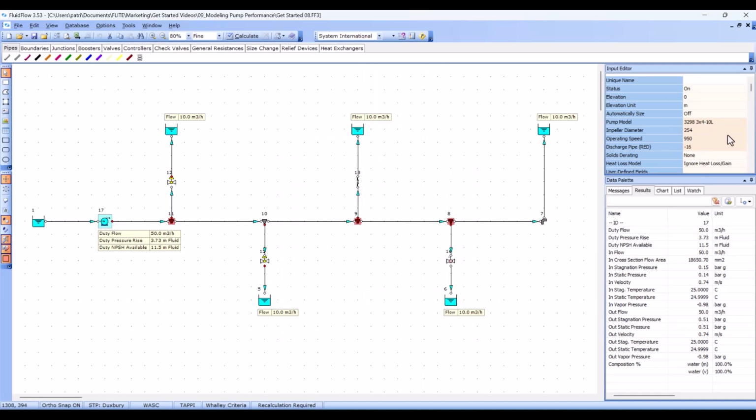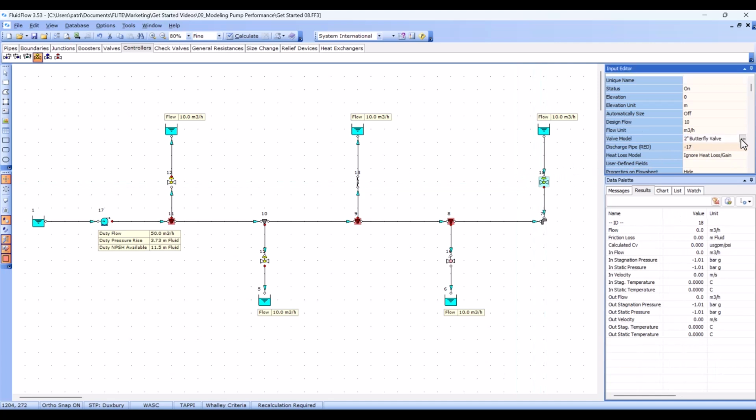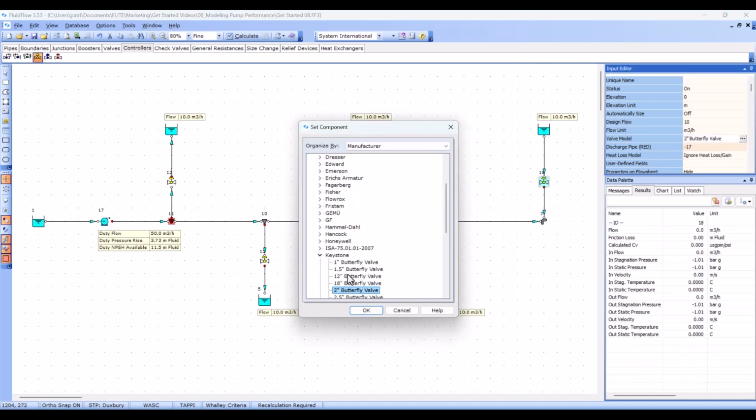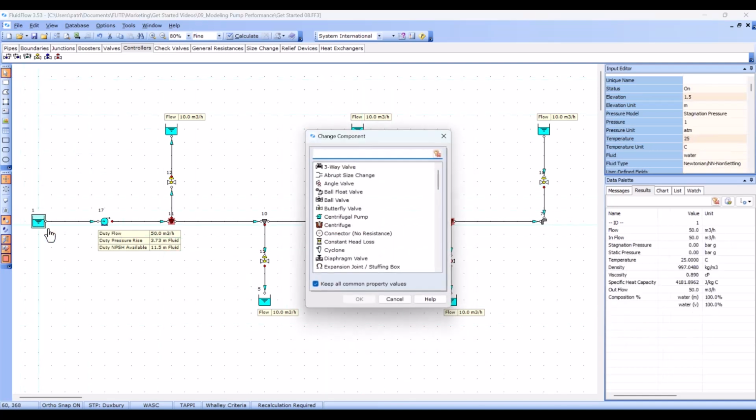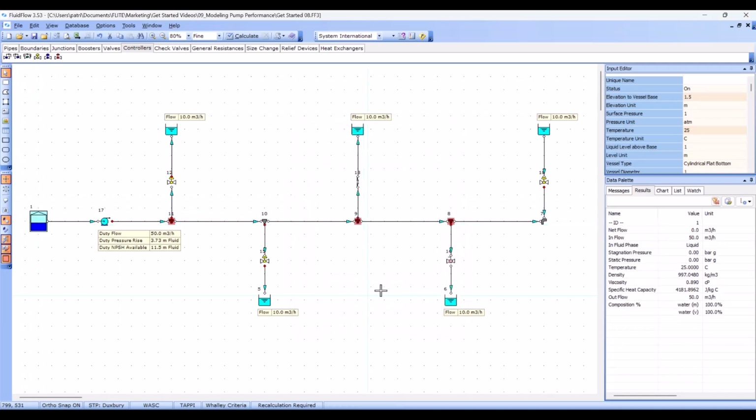With the pump integrated into the model and delivering flow based on the system and capacity curves rather than being constrained by an inflow, we can now reintroduce a flow controller to this leg. To complete the system as a circuit, we'll use a reservoir tank here in place of the known pressure node. The reservoir allows us to specify pressure and a fluid similar to a pressure boundary, but it can also accommodate multiple connections.